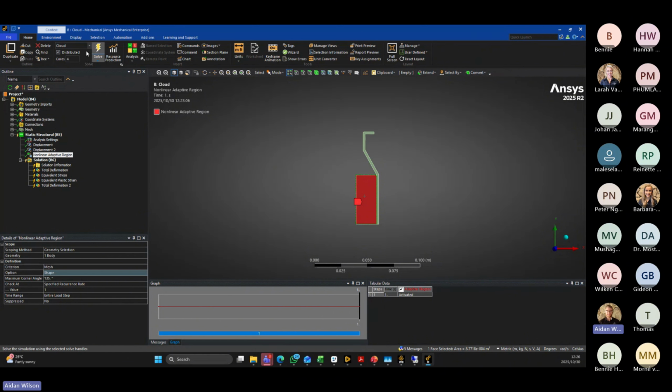Once I've set it to cloud, I don't need to worry about cores. I'm lying to you, I do need to worry about cores. I want to set 128. So this will grab two nodes of 64 cores based off of what I set earlier on. Once I click solve, this is where the magic starts. So maybe I can talk a little bit more about the process going forward.